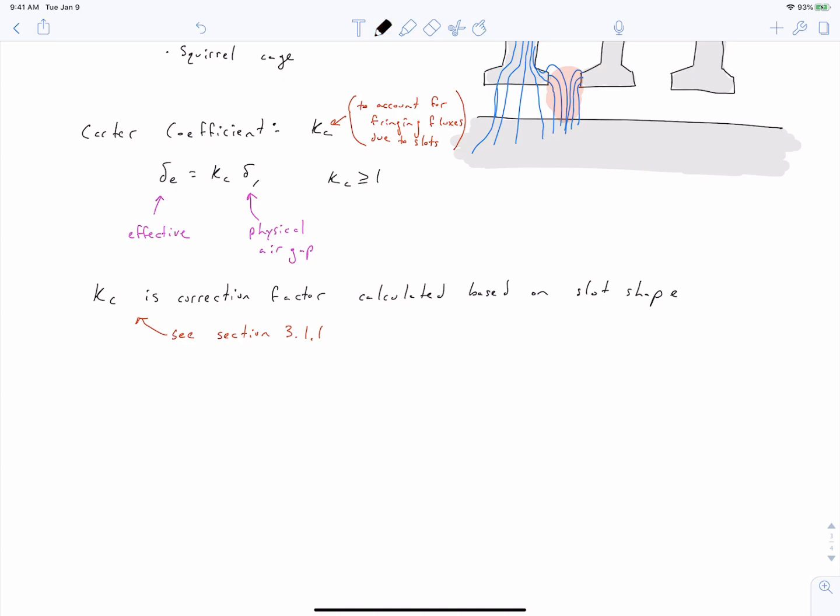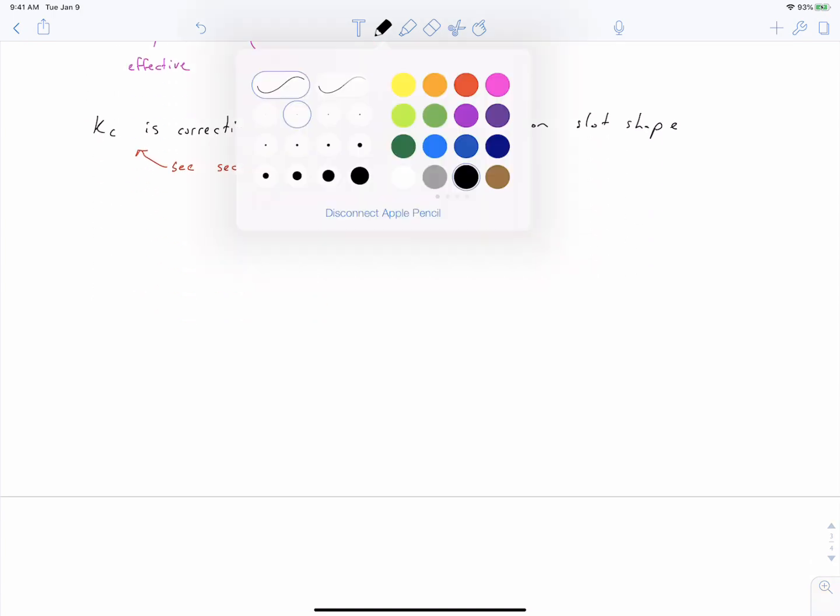And the reason that you'd incorporate this in this stage of your analysis is just to give you a more accurate permanent magnet design or magnetizing winding design. So you don't actually need to do this. You could just assume that your Carter coefficient is 1 and then go through your design process. At the end of the process, you do your detailed analysis and you discover, oh, I've got less magnetic loading than I thought I dimensioned. So then you end up increasing your permanent magnet thickness a little bit to try to get yourself back up to the right amount of magnetic loading. Well, if you use the Carter coefficient, you can reduce the number of iterations you have to have on refining your design. So these are all the steps that I have for you.